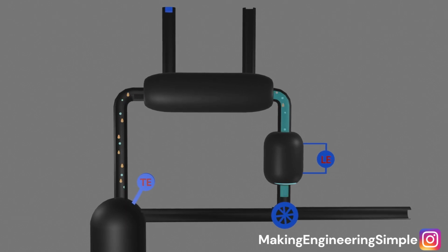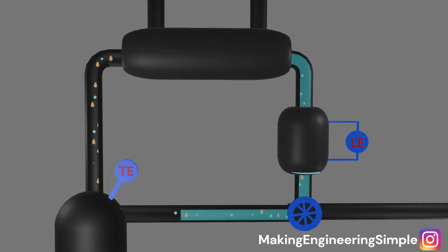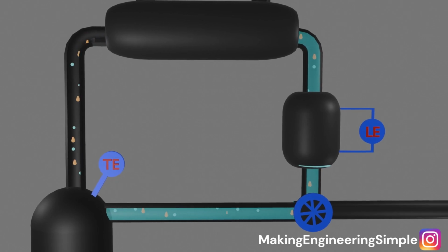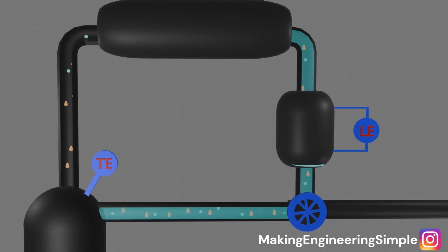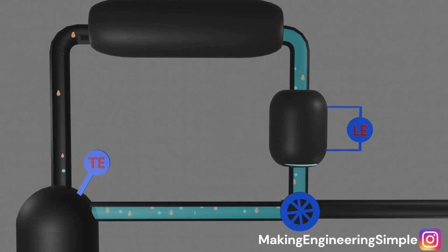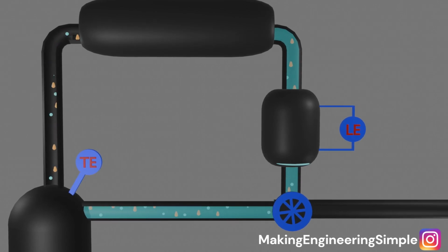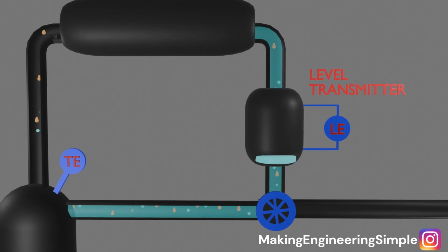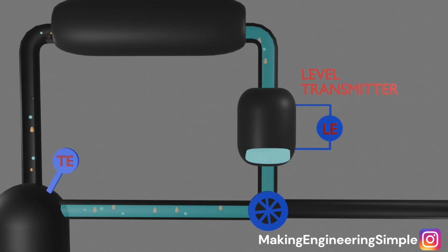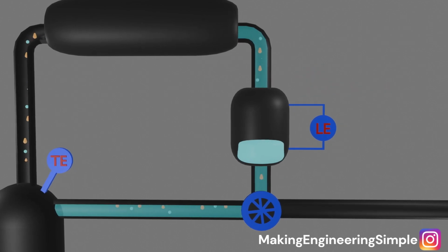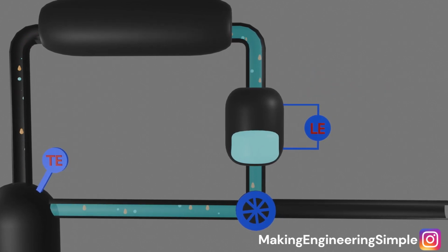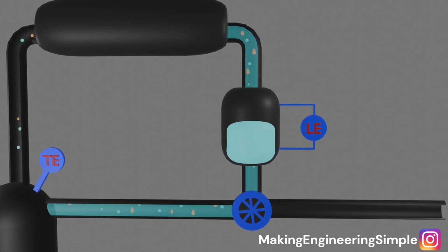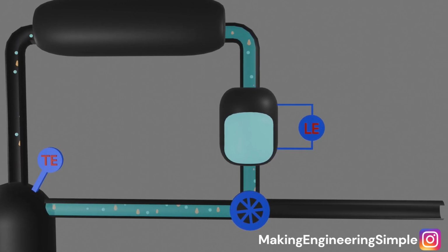Once the pure vapor passes through the condenser and turns into a liquid, it pools in the overhead reflux drum. This brings in our level trigger. A level transmitter, often using differential pressure, guided wave radar, or a float, monitors exactly how full this drum is getting. Here is the brilliant part. The column doesn't measure the spec inside the drum and then open a valve. Instead, as pure vapor continuously condenses, the level controller simply says, "The drum is getting full, open the distillate product valve to drain some out."